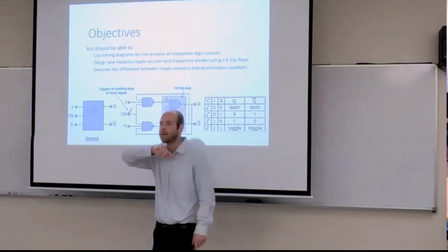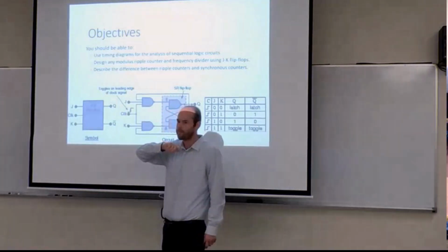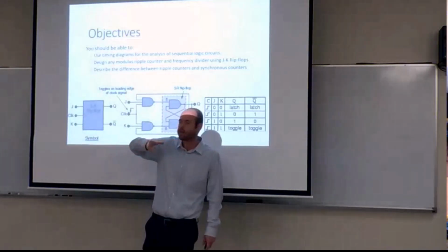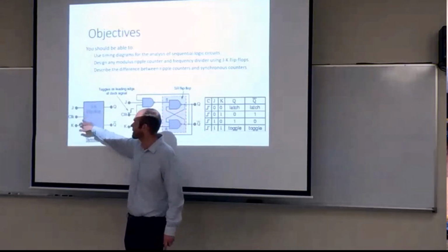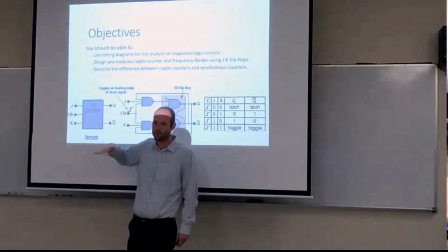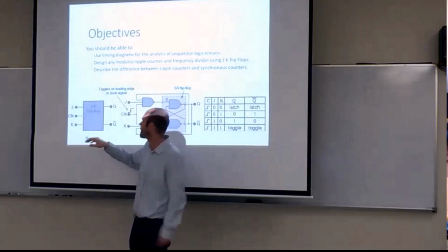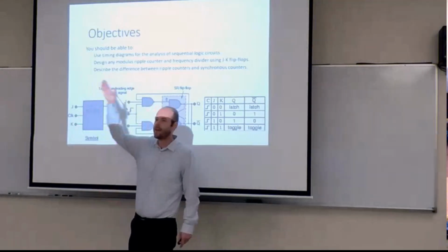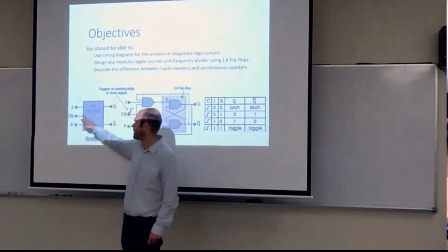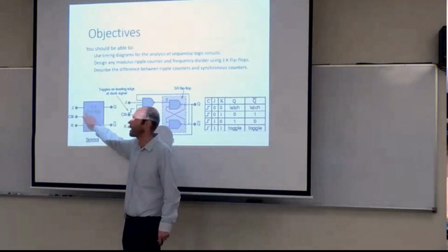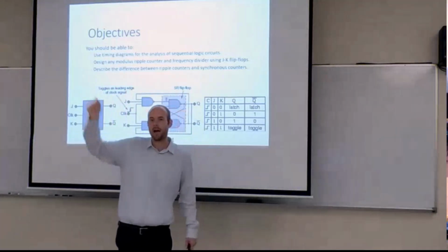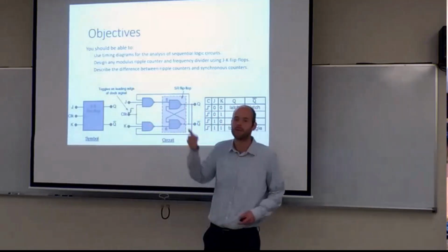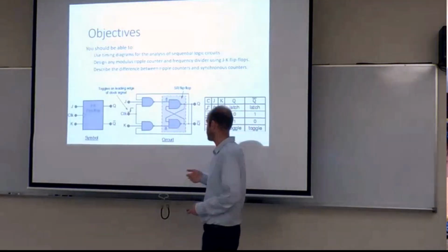Asynchronous. Yes, question. When you say edge of the clock, is that the edge of the high signal or the edge of the low? So it depends on our setup. The question was, which edge are we talking about? And that's determined by the schematic. Our clock, which will be a square wave pretty much, if you have this triangular notch, it'll be the rising edge, so going low to high. If there's an inversion bubble in front of that notch, it'll be the falling edge going from high to low. So that will be important to consider if we are putting a physical waveform from the function generator.